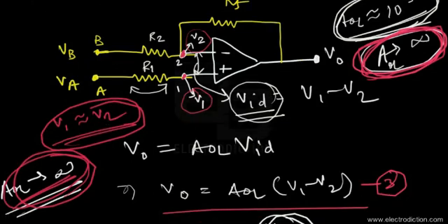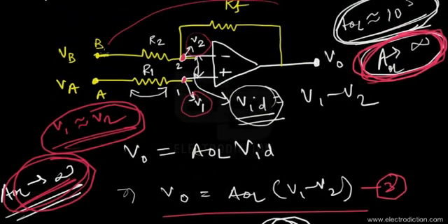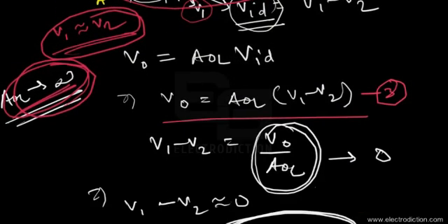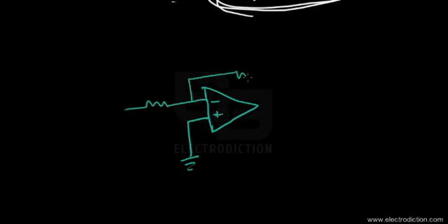Just keeping that in mind, if we go forward and modify this circuit into something like this, that I'm going to show you shortly. So there you go. If I redraw the circuit again, and ground the non-inverting input terminal and keep the rest the same. There goes the feedback resistance, that's RF, and here's the input resistance R2, and here we apply the input voltage VB at the terminal B.